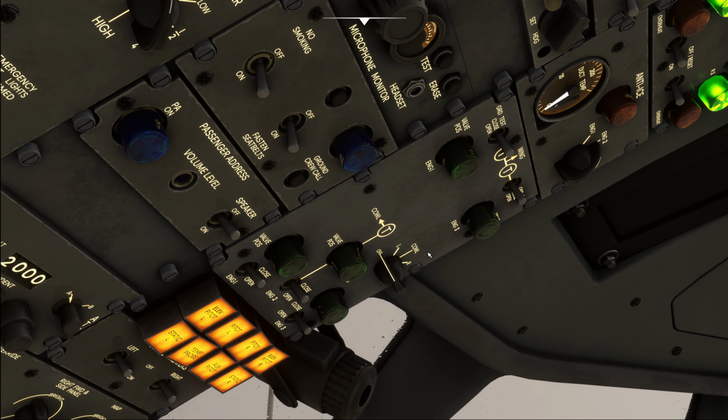we're going to select the monitor switch into the left position, ensure that the lights illuminate, and now we're going to turn the engine anti-ice on, and you can see that the lights go out as the valves are driving, and then they go back on again as the valves are in position. We also check the cowl and the right system, and we can check the same for the wings up here, and then we're going to turn the system back off and switch the engine anti-ice back off as well.